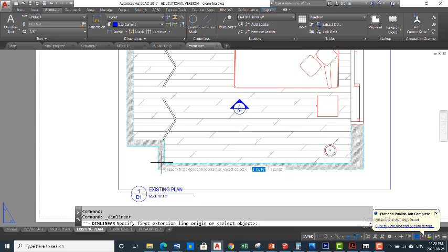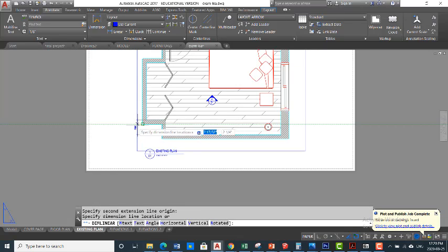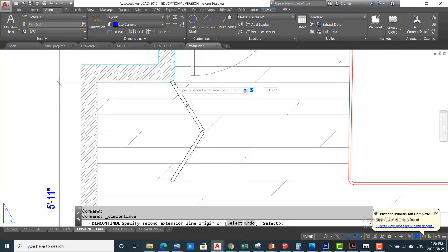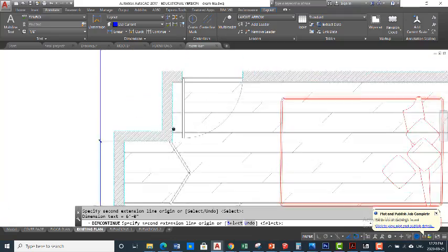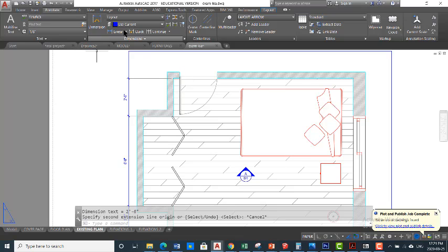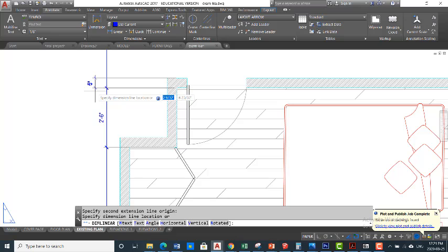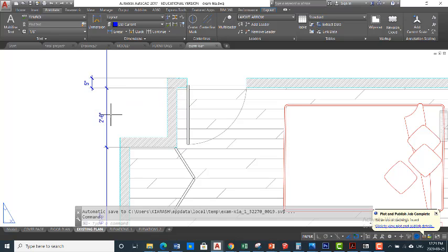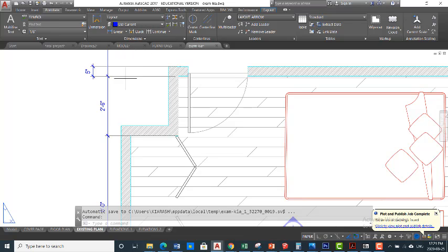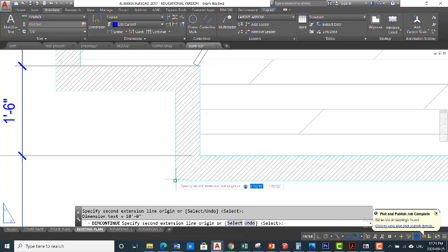So here we measure the interior walls. This is what's important for us. So maybe here, then I go with continue, again interior and interior. If I want to add the overall or the wall thickness, I do it in a different layer. For example, from here to here, but I'm in a different layer of dimension. See, this is one step. I move it that way. I go to continue. I'll go all the way here and here.